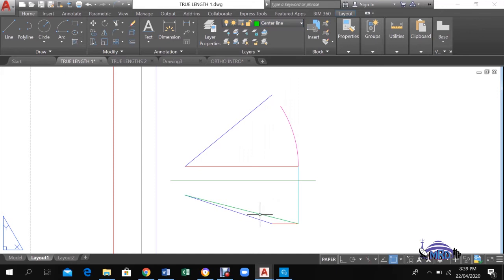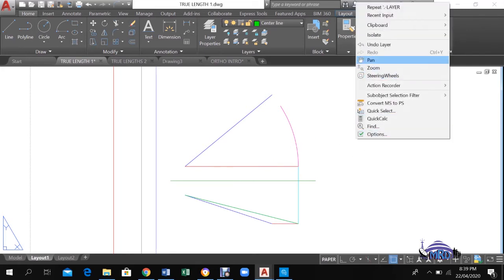However, please understand that when you draw, the true length is an outline, so it will be represented as a blue line in this instance, as the outlines are. But just for clarity, in this case, I've represented the true length with a green line. So this is construction 1, and this method is called the revolution method. We will now move on to example number 2.